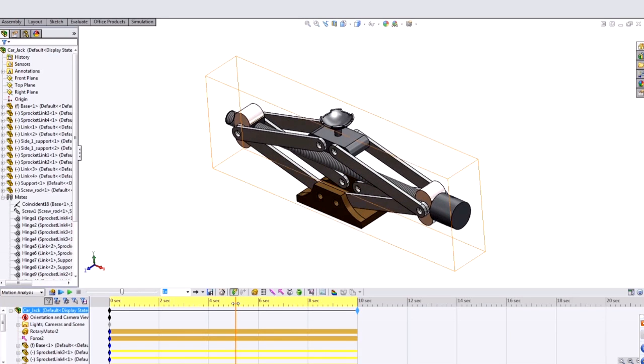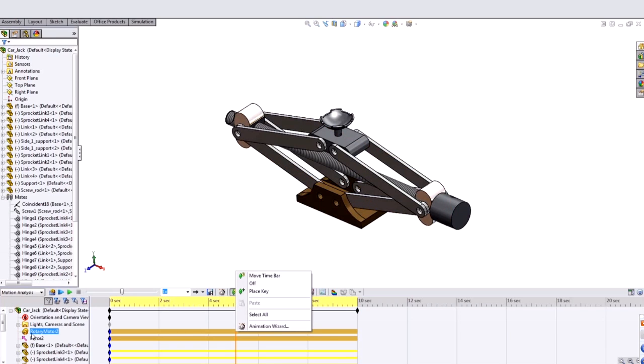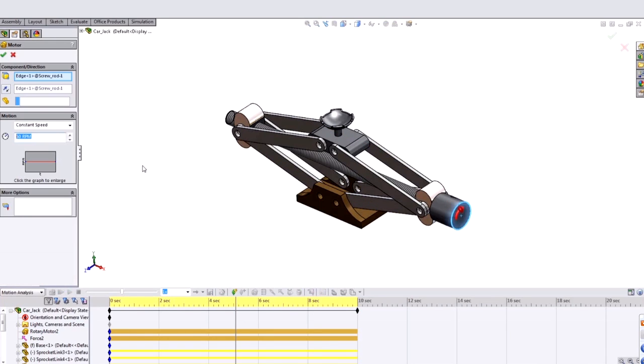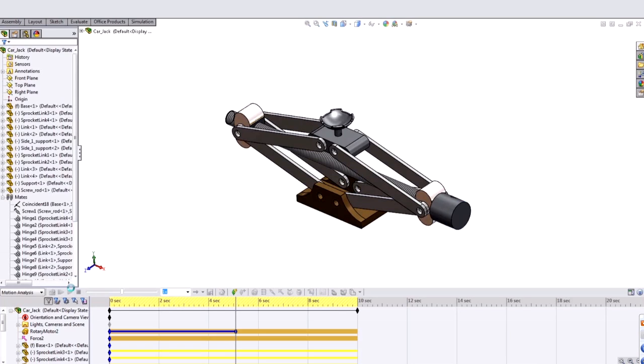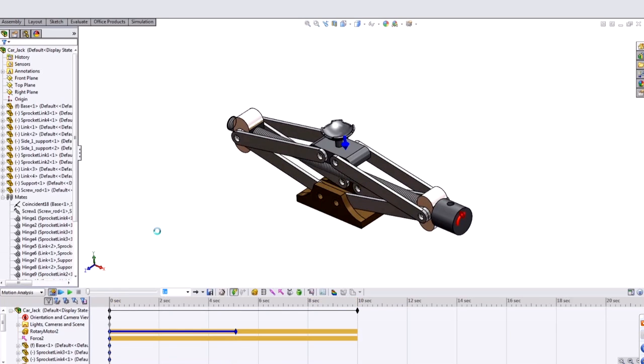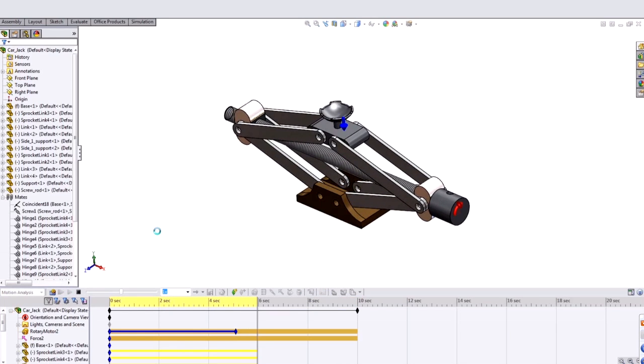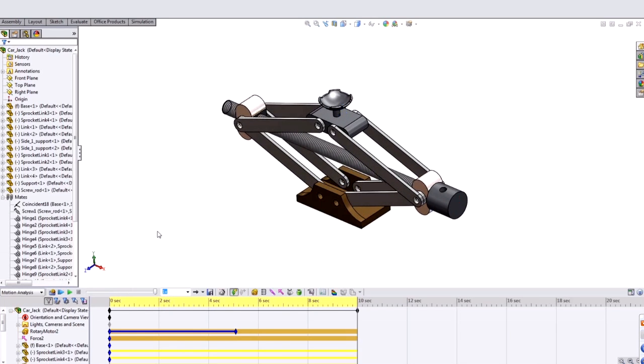Say, I'm going to spin for 10 seconds, and then at this point, halfway through, I'm going to up things to 120 RPM. So I see an acceleration occur. All right, you've got that kind of time-based control that you can adjust. But the real reason you use motion is to get numeric outputs out of it.